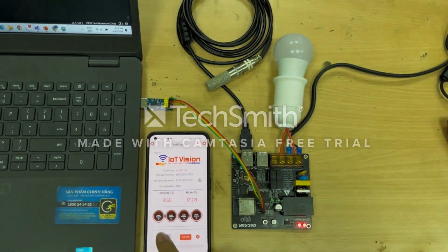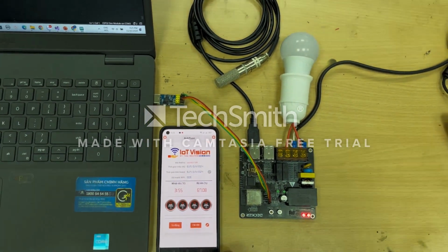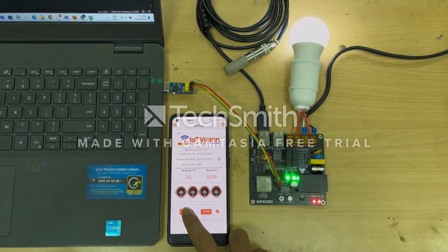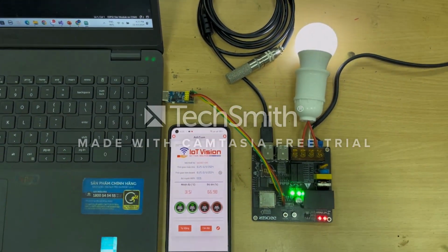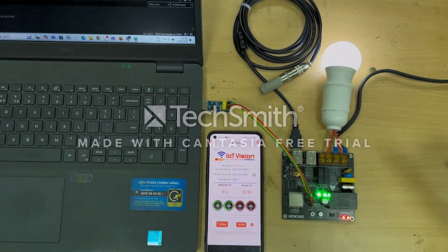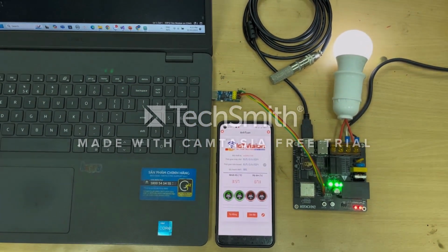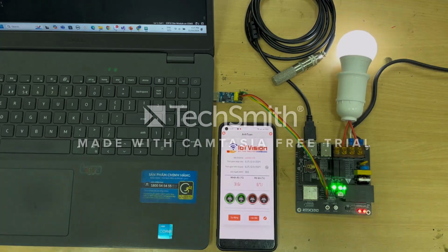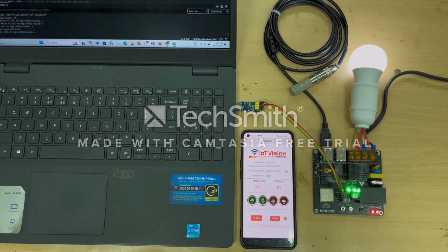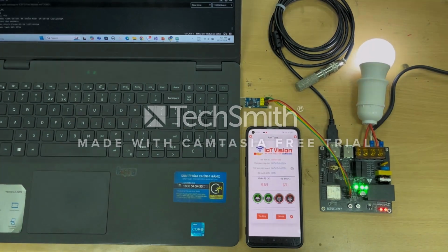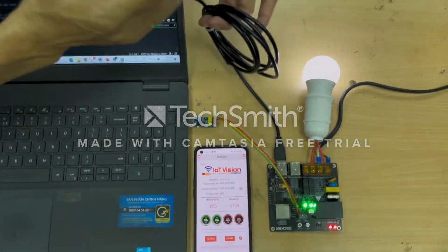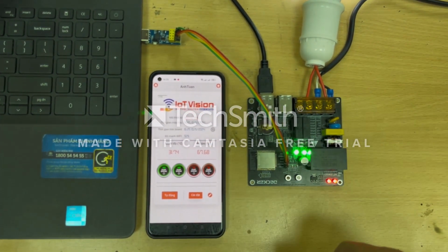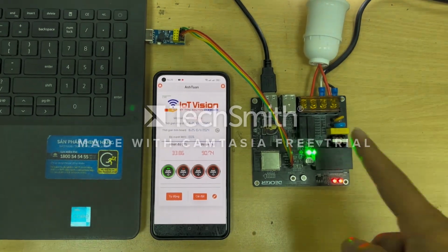and the ambient temperature increases to greater than 30 and the humidity is greater than 80 to activate the K1 load and turn off the K2 load. The result we get is the correct sequence, and the K1 light will be turned on to simulate the temperature load, and the K2 light will be turned off to simulate the humidity load. Here you can see the result.